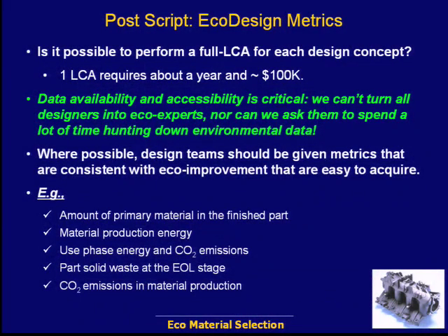But here's a postscript on the case study. Can you really do a full life cycle assessment on each design concept? Did we for the coffee maker? Remember our simple approach to eco-design. Right? We talked about understanding your product, understanding the life cycle, and then doing something about it. Step 1, step 2, step 3. But can you do a life cycle assessment for every concept? You can't. So to some degree, you have to borrow from other life cycle assessments and use your best judgment, trying to keep as much of the scope in common as you can. That's what you do as a designer.